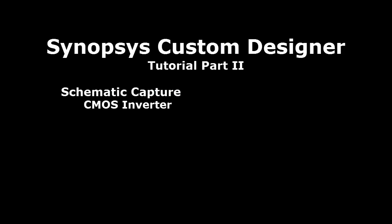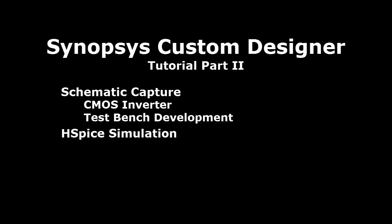In the first video, I've shown you the general overview of the Synopsys Custom Designer workflow in circuit design and layouting for masking. In this video, we'll walk through the process of creating a simple CMOS inverter. This video will cover schematic capture of a simple CMOS inverter using Custom Designer Schematic Entry Tool and the design of a simple test bench. Finally, we'll work with HSpice simulation to test our test bench.